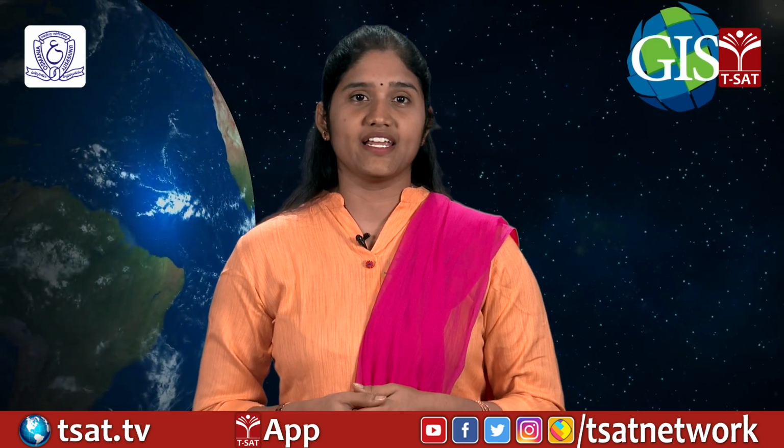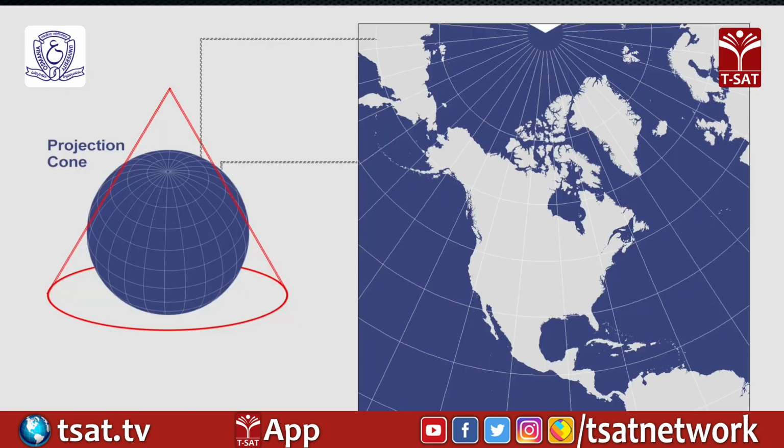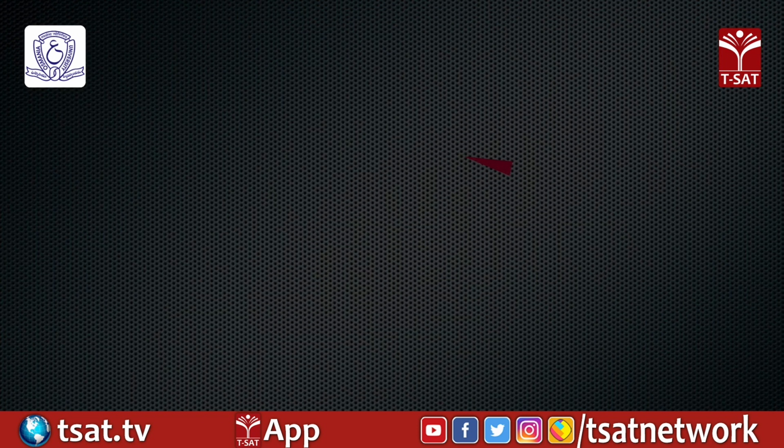Albers equal area conic. The Albers equal area conic projection has the same parameters as the Lambert conformal conic projection. In fact, the two projections are quite similar, except that one is equal area and the other is conformal.